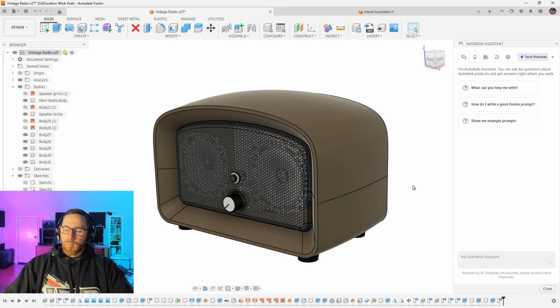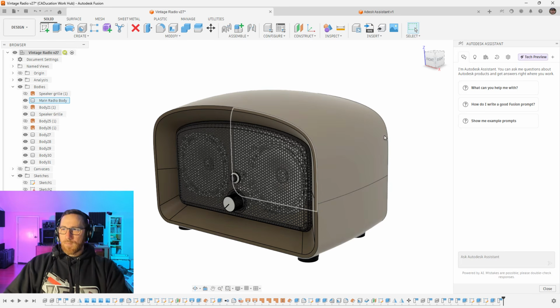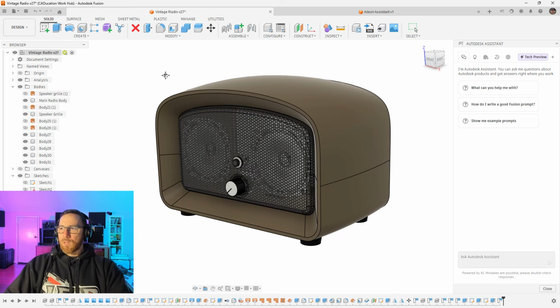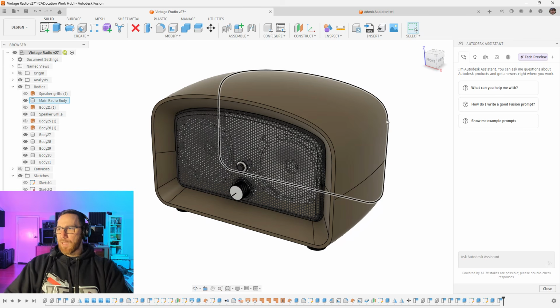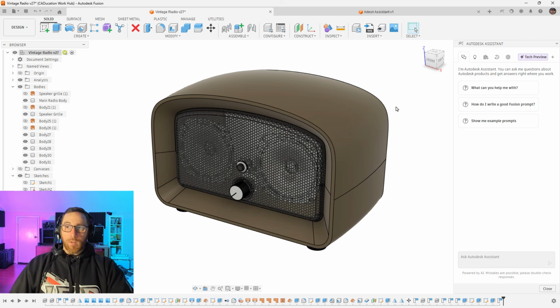There's not like a set process that you go through. But it's not really any slower than saying, okay, generate the shape for me. But oftentimes you don't know what you don't know until you start designing. Now, part of the process of the initial design, which is generally a very small part of the overall design process, is coming up with these decisions along the way: deciding where components need to go, how many buttons there are, where the buttons need to be placed for ergonomic sake and ease of access, where the cables are going to come out, and how you're going to attach certain features.